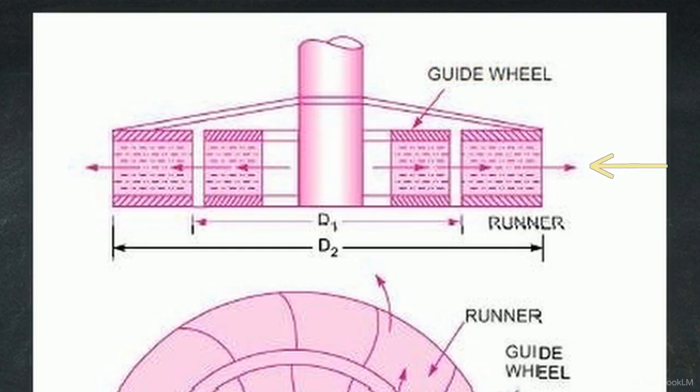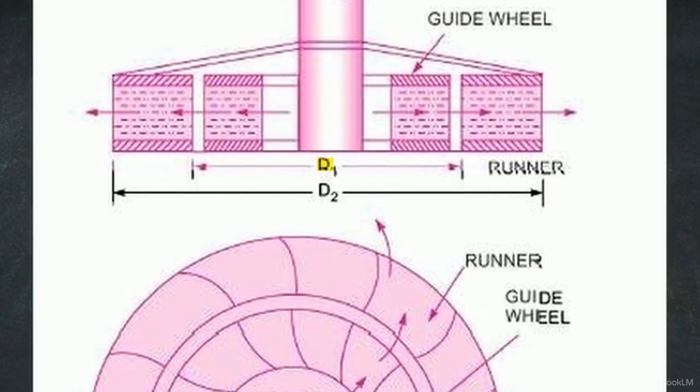Horizontal red dashed arrows show the fluid forced radially outward from the guide wheel, moving away from the center into rotating runner channels. Because water moves outward as the machine spins, centrifugal force inherently assists the flow direction through the blades. This creates a critical geometric rule, visible here in the dimensional brackets. The inlet diameter, d1, is strictly smaller than the outlet diameter, d2.